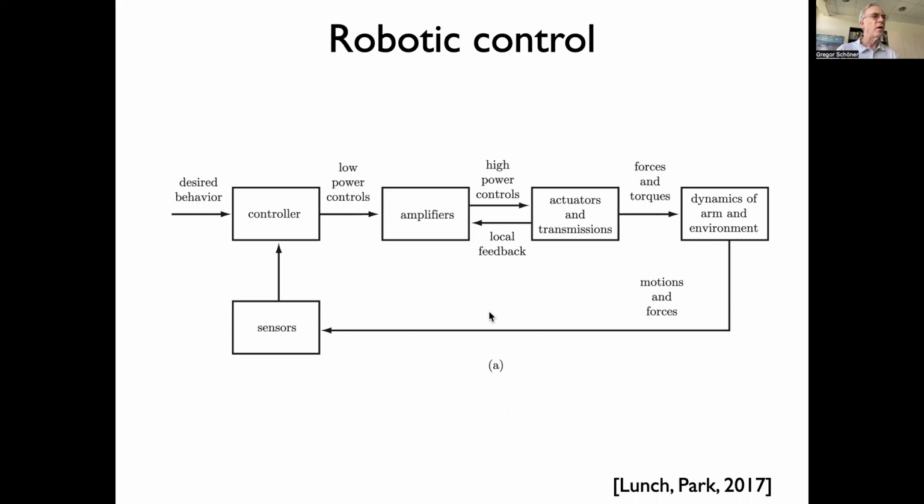In all of robotics, there's this very special thing here, and I'll not go deeply into that, in that there is another feedback loop, a fast feedback loop that controls how the electrical signals you give to the motors translate into their actual force production, how that is regulated. Because that works so well, you can theoretically know what kind of current to send to the amplifiers in front of the torque motors to get what kind of torque.